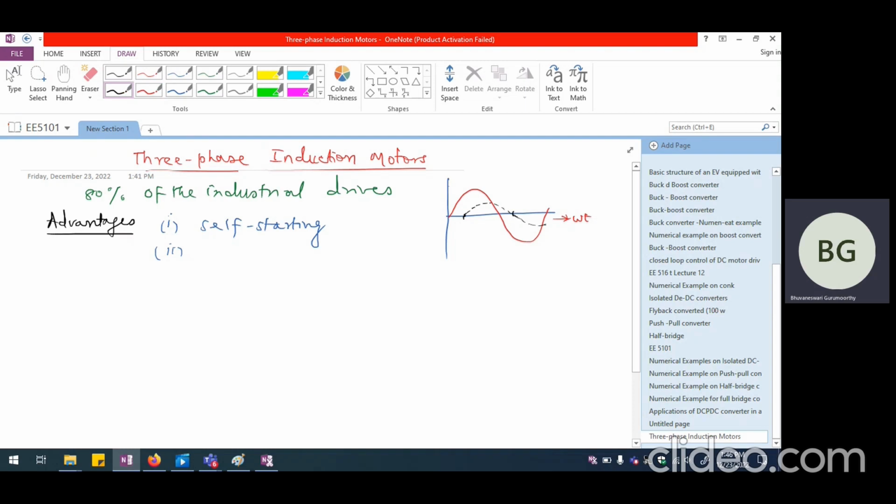What is being carried by the motor will be somewhat like this. So if we are looking at the product of voltage and current, which is the power. So let us say this is the voltage and this is the current. So if we look at the power, we are going to see that voltage is positive here, but until this point, the current is negative.